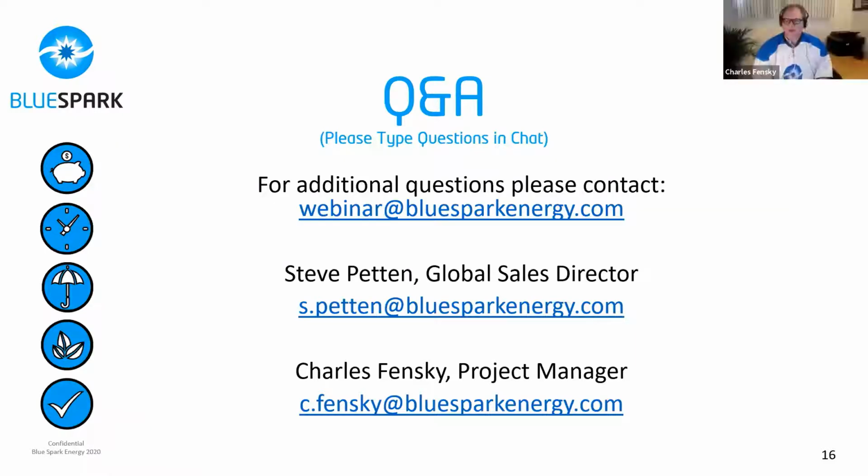It's a good question. So I'll dive into a little bit of the physics of how it works. We have showed you that wireline tool earlier. You also notice that we're actually has to be in a fluid so that the shockwave can actually transmit away from the tool and actually get to the scale or the item that needs to be cleaned. So wherever the application of high power shockwaves is going to be needed, in that particular location, you have to be in fluid. Fortunately, we don't discriminate what kind of fluid it is, as long as it's water or an oil. Unfortunately, it can't be gas, just like you'd have in your car where you have a shock absorber absorbing that shock. If you have a gas at the point of treatment, this won't work.